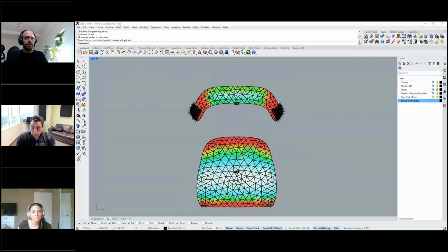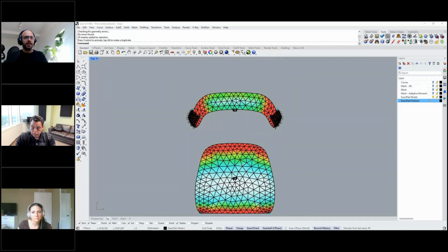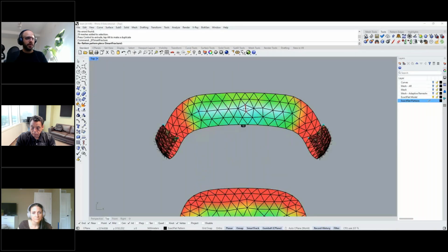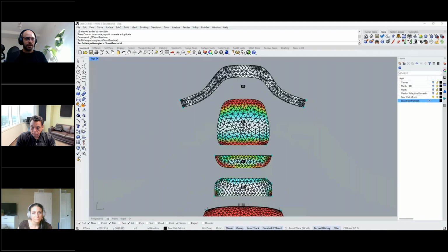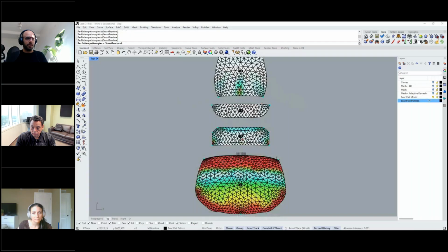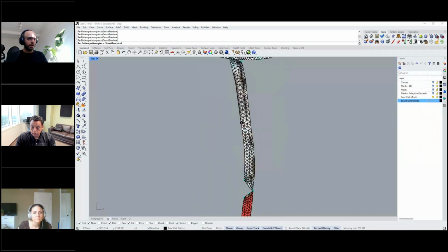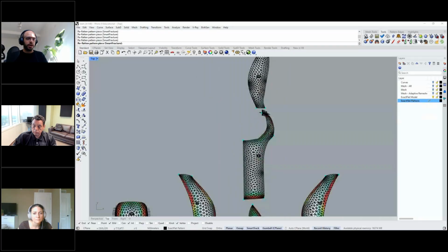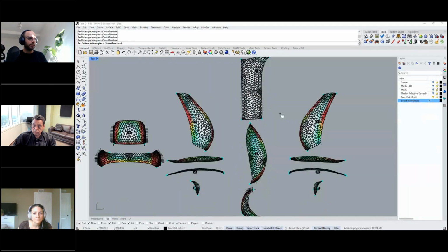In order to do that, we can run the ExactFlat pre-flattener tools. So I'm going to select the Smart Fracture command. This command will extend my pieces on the ground or on the table. This will still not give me my final production-ready patterns yet, but it will prepare my flat patterns for the optimization process that will come afterwards.